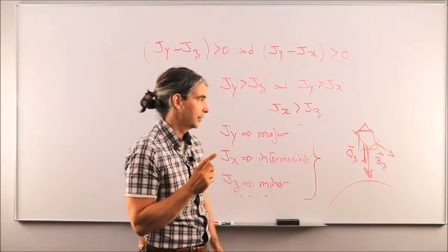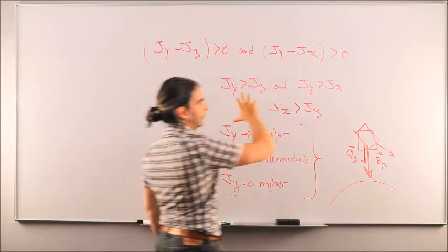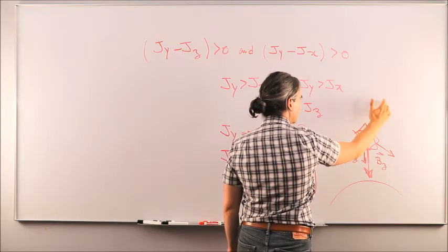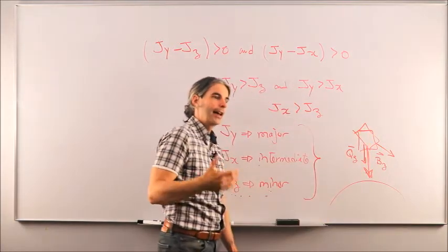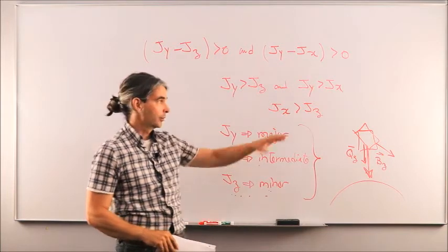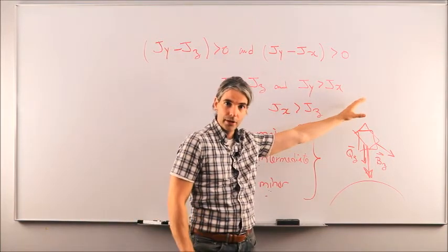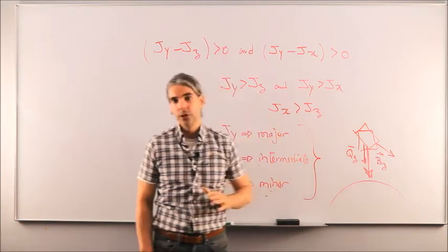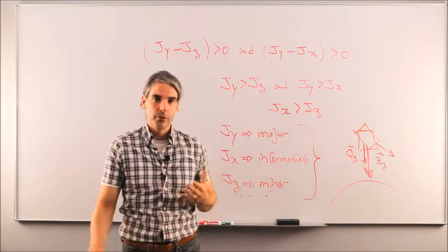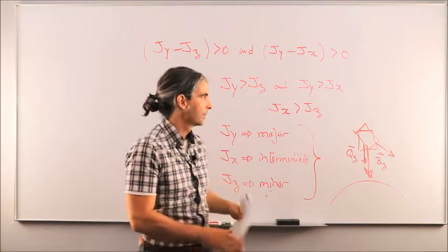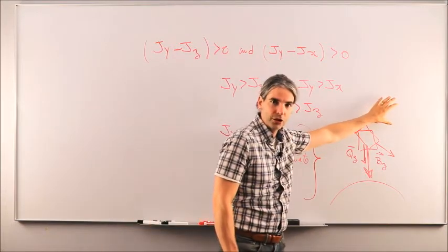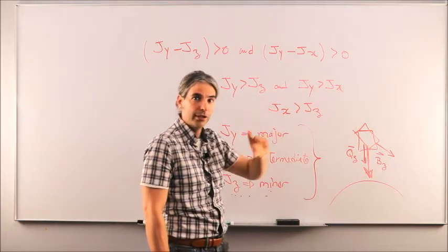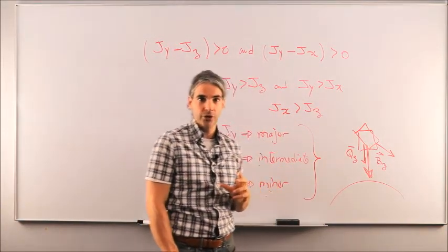And that comes down to the expression we had obtained on the right-hand side of my three equations, where I had the gravity gradient torque in the body-fixed reference frame. And I had then told you that we're going to use an alternate expression for gravity gradient torque in body-fixed. That could be derived from the first expression, but that was up to you to do that derivation because it was one of the problems in this chapter. Now, if you go back to this alternate expression, you will realize that the torque is actually proportional to the difference in principal moments of inertia.